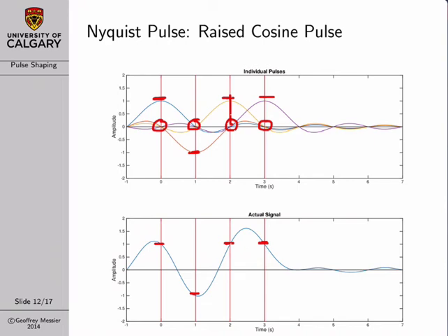Right? So you can think of these sinc pulses then, as long as we transmit one new sinc pulse at exactly every symbol interval, it's going to line up with the zeros of all the other sinc pulses, and we have 0 ISI, or 0 intersymbol interference.